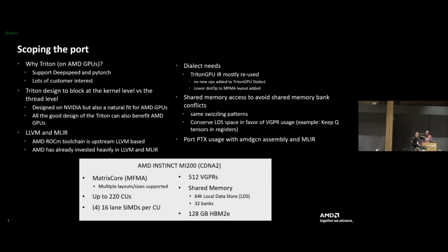Beyond that, we've got all the different layouts, right? Our shared memory on AMD GPUs is very similar in design to the NVIDIA design, so the shared memory layout mostly just worked for us as well. We do have different sizes of shared memory. On ours, we have slightly less shared memory, but we have more general purpose registers.